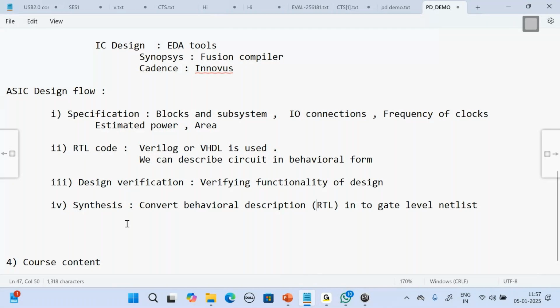There are two things again: logical synthesis and physical aware synthesis. Both we will do in our course, but I am discussing logical synthesis. Logical synthesis requires three files. What are they? One, no doubt, you require as input is RTL, which is nothing but the Verilog program you have. What is the second thing? See, you have to convert your RTL description into a gate level description, right? What gates do you have to use? Who will give that?